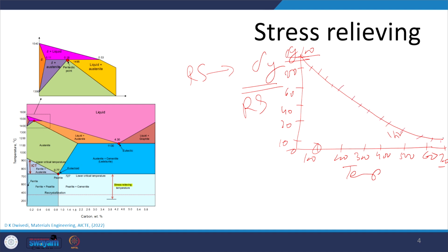Okay. Increasing temperature means reducing the residual stress. How much? 80% of the yield strength, 60% of yield strength, 40%, 20% and 10% of the yield strength. So, that is the left out residual stress due to the high temperature exposure. It may be absent also, it may be completely relieved. So, what happens when the temperature is increased? The yield strength of the material comes down, whatever locked strains are there get relieved, and so the residual stress is relieved. Okay. This is one case.